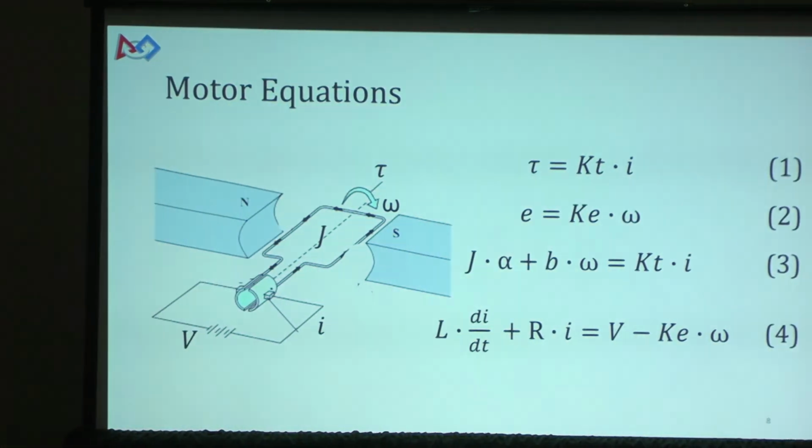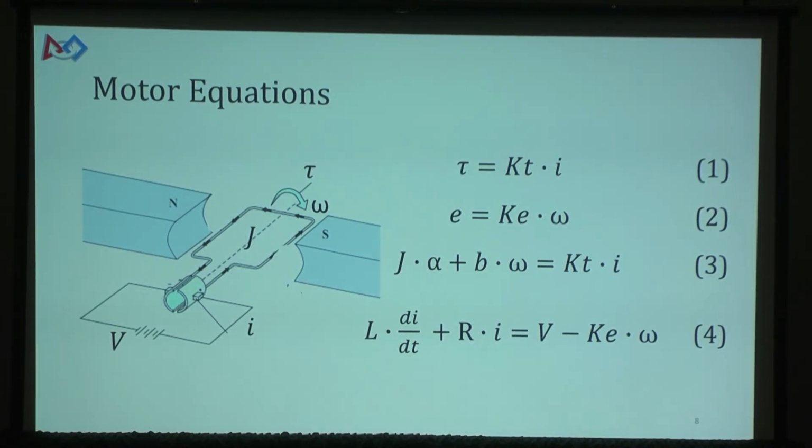For low speeds it is linear, for current, and for high speeds it's not. For voltage it's practically never linear. We chose that particular formulation of the equations at the beginning. We chose that formulation just because it is strictly linear and strictly straightforward. If you start with current and angular velocity as the independent variables, it's simple; if you start with voltage or torque, then it gets fairly difficult to separate things out to measure the other two variables.